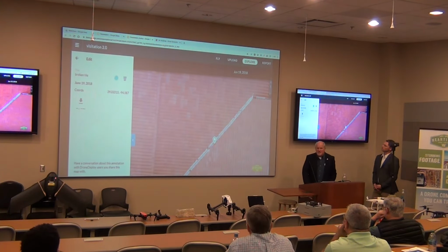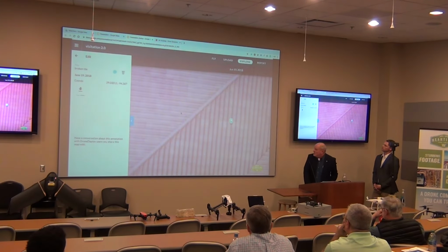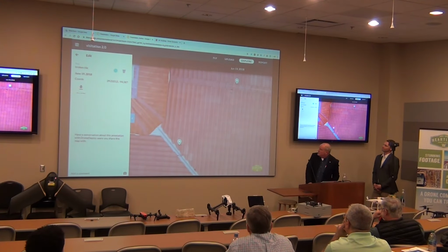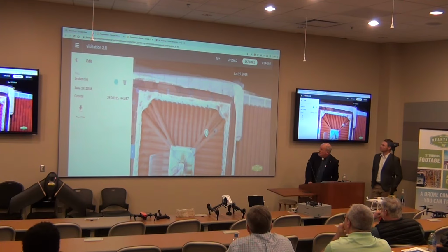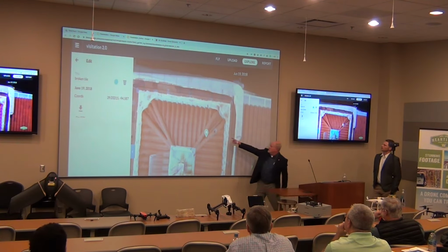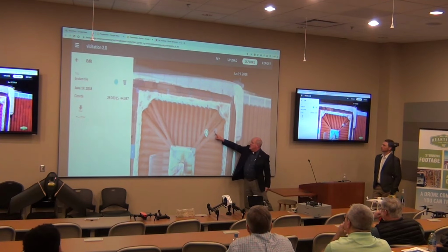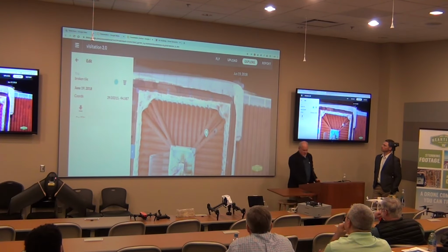And so I followed the pieces. I just looked for broken pieces, and I made an annotation at each of these places. There's a cracked barrel tile. There's missing tiles. There's a hole. In fact, they didn't even repair this with a real barrel tile. They just repaired it with mortar, which then a hailstone cracked.